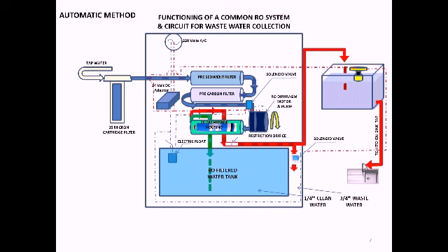And this tank can be fitted with a NO float valve, a normally open float valve. The wastewater would first go into this overhead tank. Once the tank gets filled, this NO float valve will go to the circuit close point, and it will complete the circuit for the solenoid valve, which would drain the water the way it was doing before putting the overhead tank, again back to your sink.